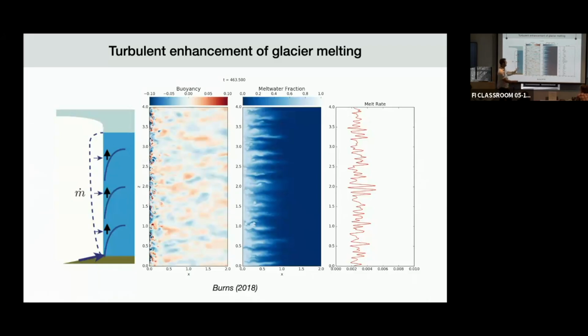So you could just get like a laminar profile of water flowing up, but it's sort of like the Kelvin-Helmholtz instability now on its side, where we have this freshwater layer that wants to go up, and we have this static layer here, and that shear interface becomes unstable, and that's what causes these little rolls and triggers turbulence in this flow.